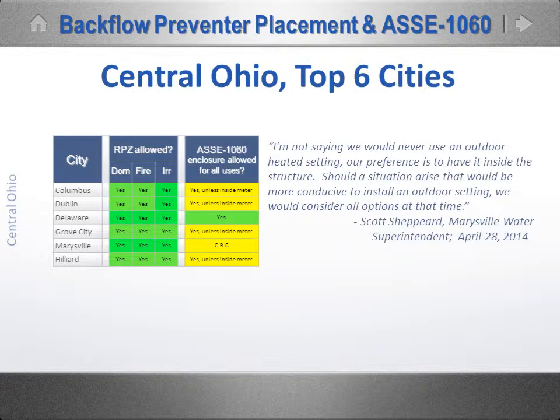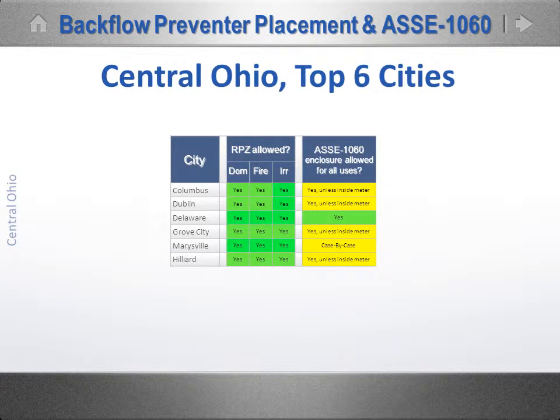So let's look at Columbus. And by default, Dublin, Grove City, and Hilliard. These guys demonstrate a profound willingness to accommodate. But there is often a problem because the legacy method in Columbus is to install the water meter indoors. Given the fact that the meter is indoors and the fact that they want the backflow preventer to be installed immediately after the meter, placing the backflow preventer indoors is simply practical from both a water security and plumbing efficiency point of view. It's probably fair to say that when this practice began, a lot fewer RPZs were being installed on domestic lines. But my, how things have changed.